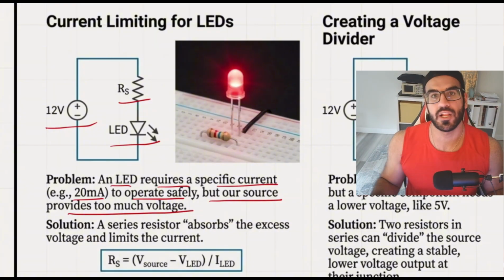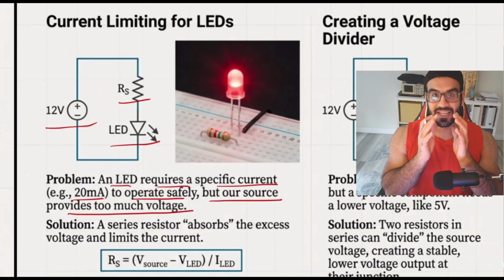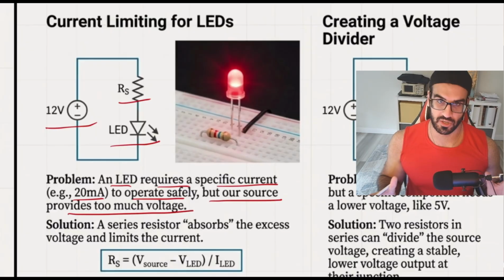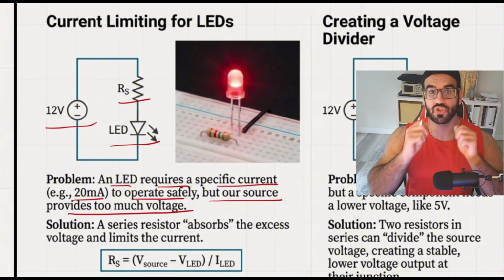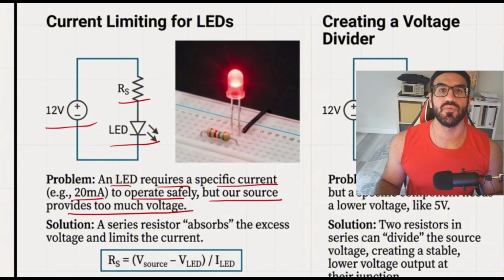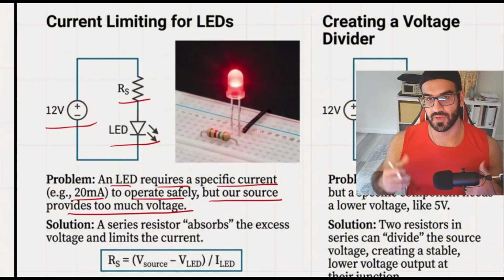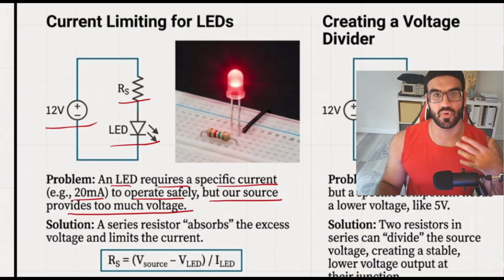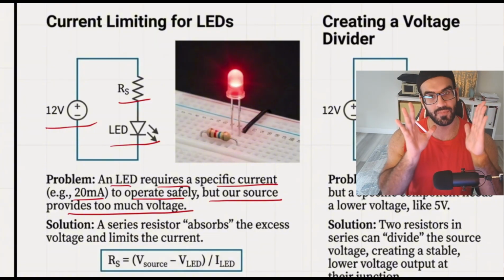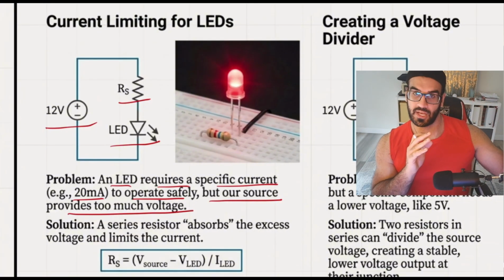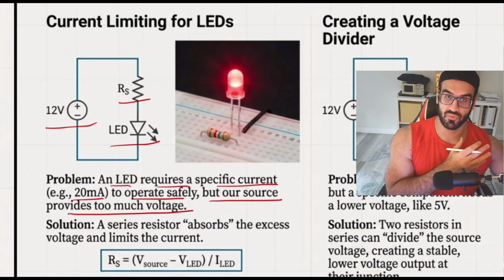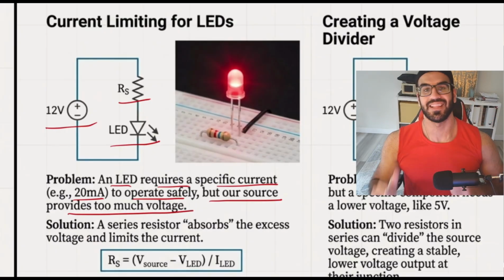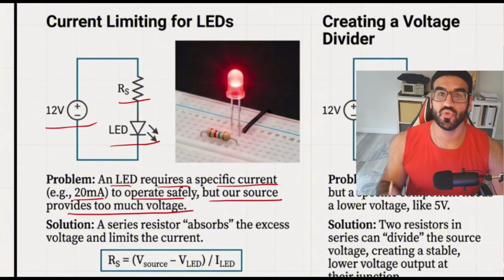An LED or any kind of component has a limit in handling the current itself. So if you inject too much current in your LED, it would break down. Maybe you smell that, or maybe you hear banging or noise, or anything, your LED is going to go down. That's why I have to limit the amount of current. I would like to use the full potential, but right now I have to limit it. That's why I'm going to use the RS.